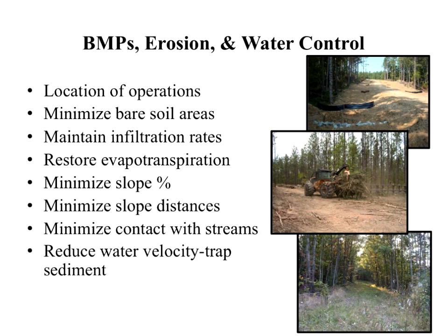Culverts are a good example where in Virginia, there are at least 3 different ways that we calibrate how large of a culvert we might need for water control. And again, I can't say that one size fits all. But if you do see that your standard BMP, you're having trouble with it blowing out, I would say this would be a good time to look and see how unusual that rainfall event was. And then if it really wasn't that unusual, then that particular standard might need to be increased. You might need to use a little bit larger culvert for that.